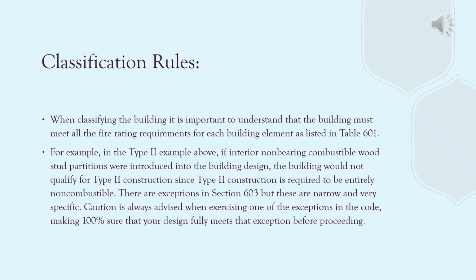When classifying the building, it's important to understand that the building must meet all the fire rating requirements for each building element as listed in Table 601. Table 601 is going to be a critical table to get familiar with.